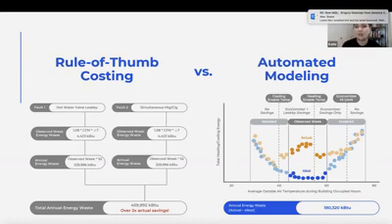The other option is to do more of a regression analysis, automated modeling, where you have a true baseline energy consumption if everything is operating as it should versus actual. So actually taking regression analysis, looking at during this time when this problem would happen, looking at your TMY2 weather data and coming up with an actual minus an ideal cost and sharing how that information is acquired. So that's very important to ask those questions if it's important to your campus.